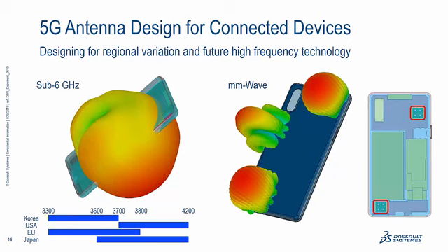When we think about millimeter wave, so high frequency integrated arrays effectively, here because the antennas are becoming so physically small, we're likely to see much stronger effects of manufacturing errors and tolerance. So we really have to make designs that are more resilient to things like shifting around mechanically, to thermal deformation. So we see a lot of multi-physics effects coming into play. Co-design becoming more important. And this is something that Jonathan will talk about at the end of the presentation. So I'd like to focus on each of these topics in a bit more detail.